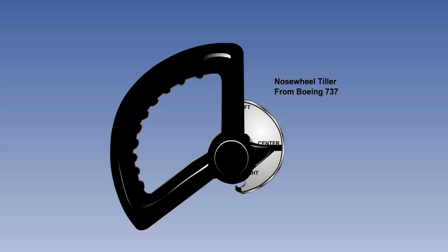First, regarding VMCG, nose wheel steering may not be used when establishing the speed, since its use would artificially reduce VMCG, and on a slippery runway, nose wheel steering is likely to be ineffective at speeds well above taxiing speed, so would not be able to control the aircraft directionally at or above the stated VMCG.